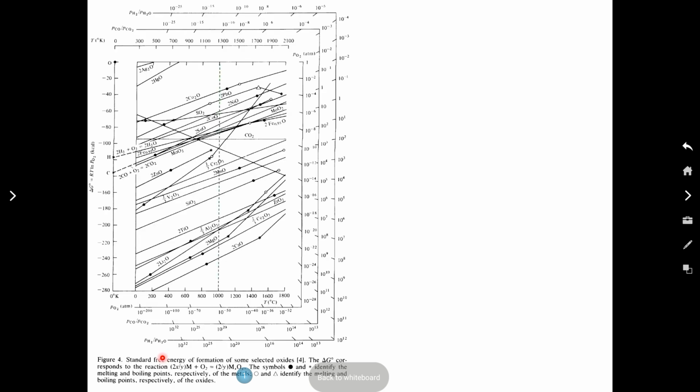So how does the Ellingham diagram work? You probably know that. I think this is silicon dioxide looking at 1000 degrees Celsius. So you draw a vertical line to that equilibrium boundary, and then you can use this reference point O, H, and C to calculate this quantity. So you can use O to calculate PO2. So this is how it's done.